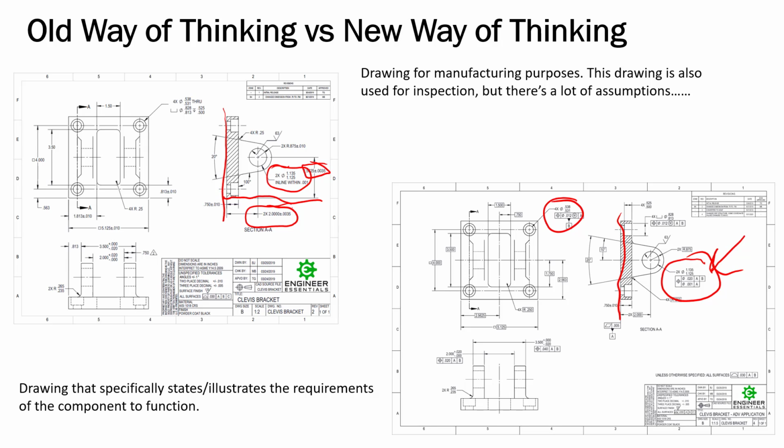Well, converting this over to GD&T, we're still holding, down on the lower frame here, back to A. This is composite, so it's holding the 2 holes together within 1/1000th. So that is holding them in line within 1/1000th, so thousandths coaxial to each other. But we've put on here that we don't have to be so tight back to the datum reference frame. So we're within 20 thousandths back to the datum reference frame. Well, that's something that we wouldn't have been able to do over here. We can't come back to this global datum reference frame and put these dimensions on here. It doesn't happen that way with a coordinate dimension print.